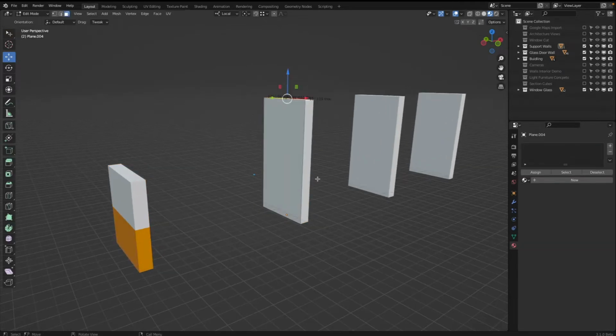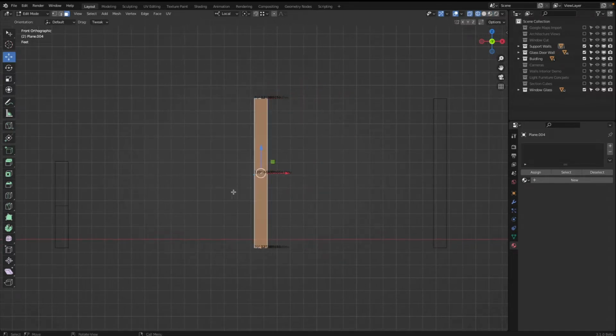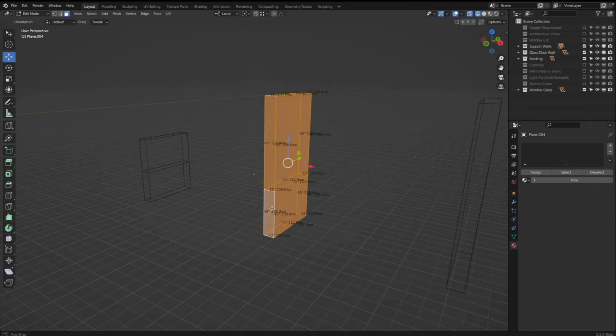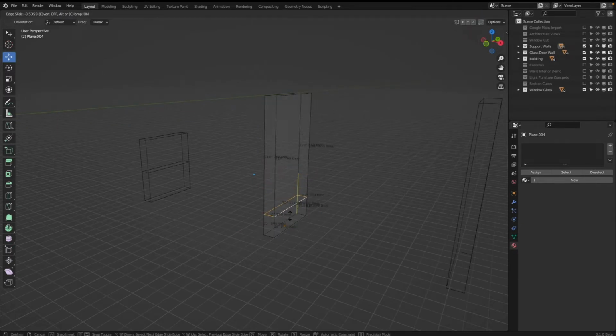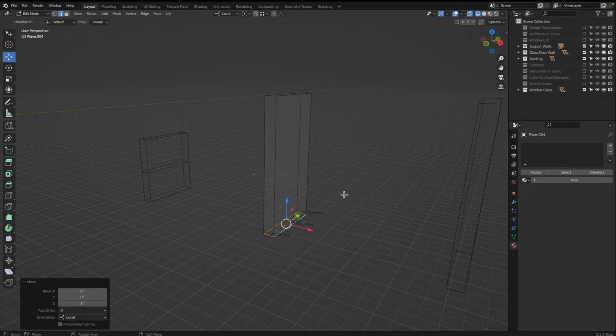So let's go to here. Let's assume the Control R for loop cut doesn't work. In edit mode, I can press K for knife. Then this is the x-axis, and then cut through, C, click enter. There's my loop cut. Also here, Alt click on this edge, GG, GZ, what was it? 1 meter, not 1 inch, 1 meter. There.